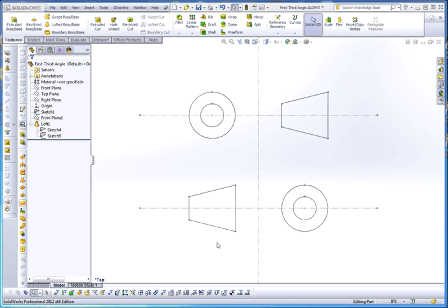So in regard to projections, for the third angle projection, think about this as a fold line, and that's the same for the first angle projection. In the third angle projection, you're actually folding this part over here, you're folding this down. If you fold this down, that turns into the right view. It will always be the right view, whether it's first angle or third angle. It just depends on where you put it, but this is the right view, and if you fold that down, you can see how that works.